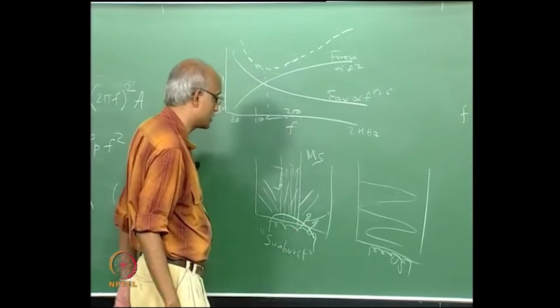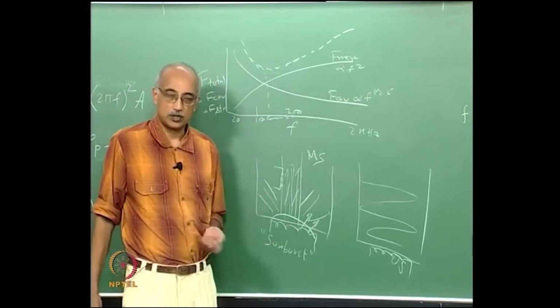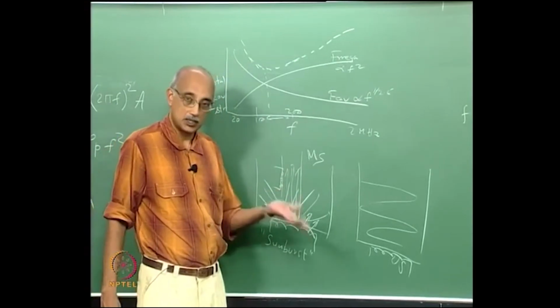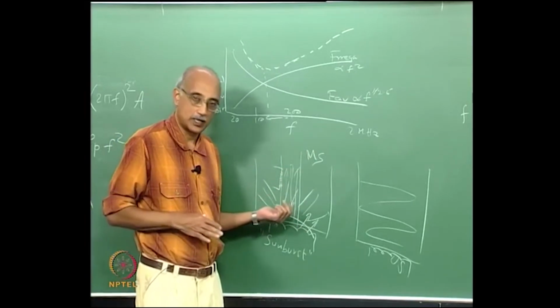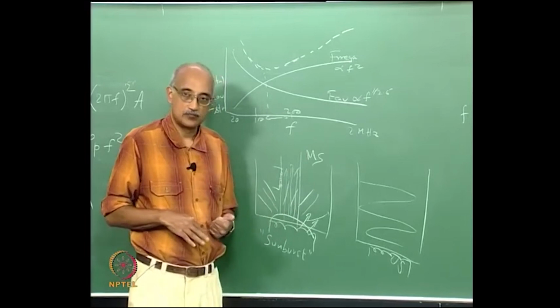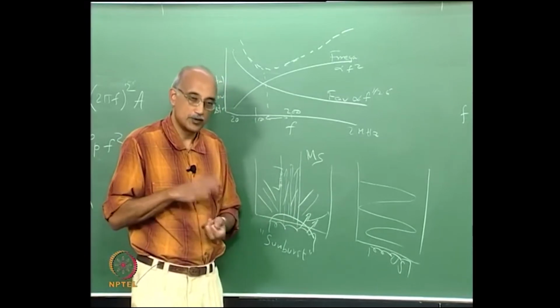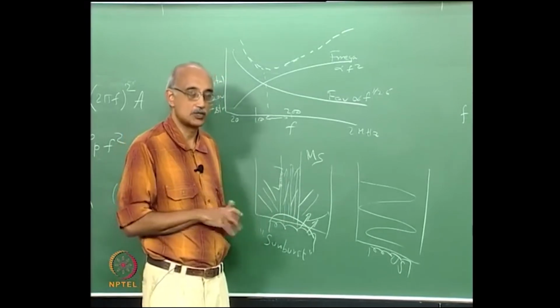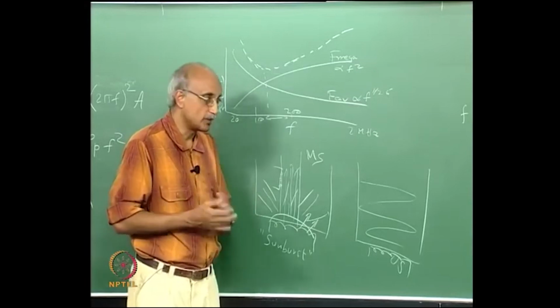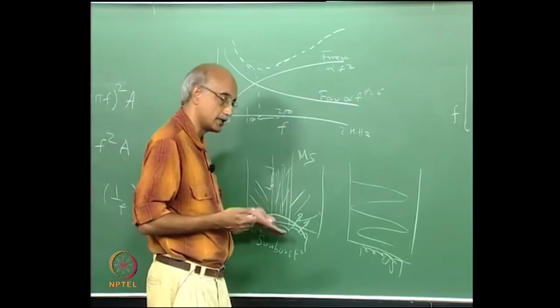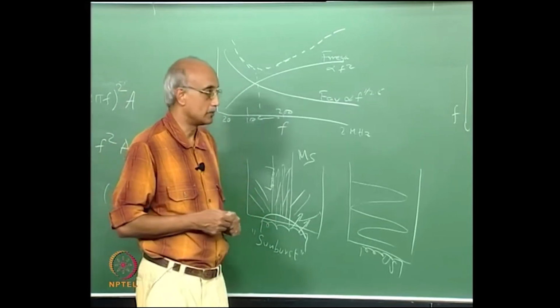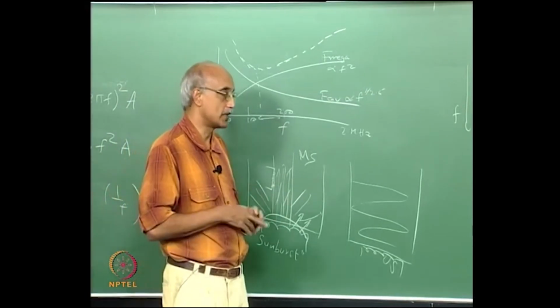So, this technique was really the fallback for the megasonic cleaning industry till very recently, when we found that sweeping the frequencies is even more effective than the hemispherical design, which comes with its own efficiency disadvantages. A flat transducer is always more efficient to manufacture and to use compared to something that is rounded. So, we have made some significant advances in that sense.